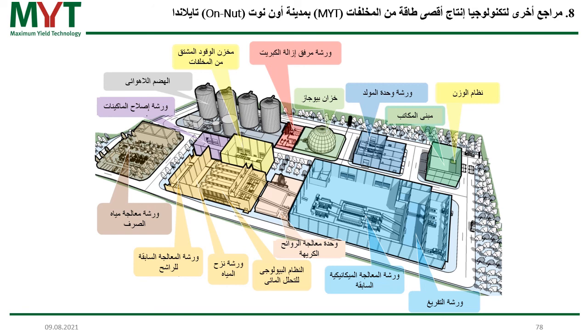Then you go over to step number 2, which is biological conversion. So you have the biological hydrolysis system, which is the mixing. You have the dewatering workshop, which is the presses. You have the leachate pre-treatment workshop, where you take care of the process water. Then you have the wastewater treatment workshop, which is the cleaning of the waste water.